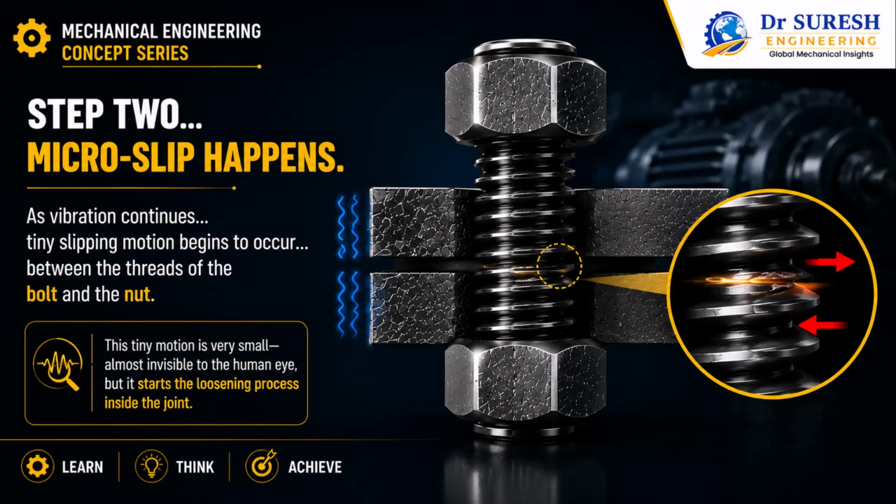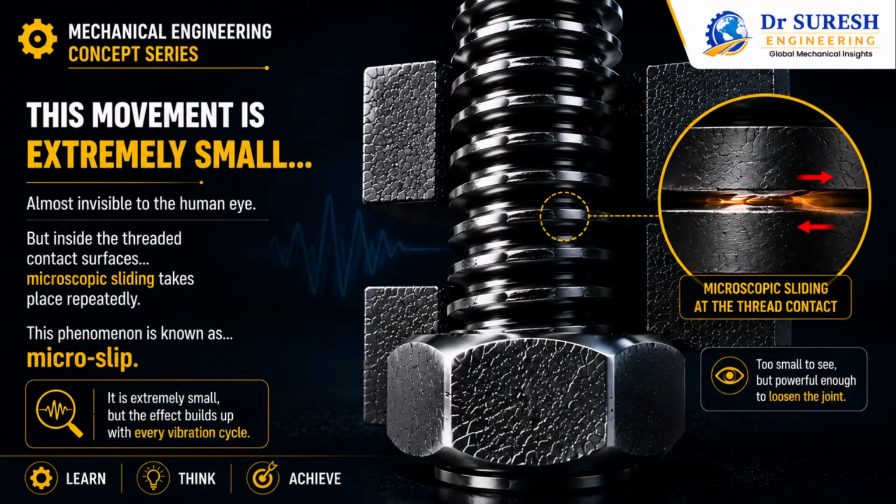Step 2. Microslip happens. As vibration continues, tiny slipping motion begins to occur between the threads of the bolt and the nut. This movement is extremely small, almost invisible to the human eye, but inside the threaded contact surfaces, microscopic sliding takes place repeatedly. This phenomenon is known as microslip.